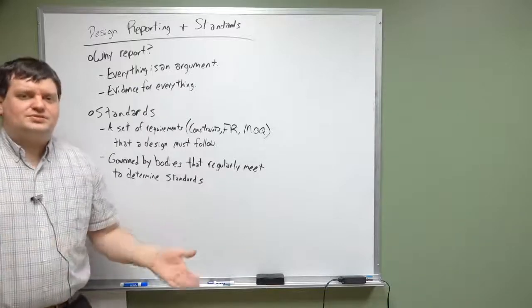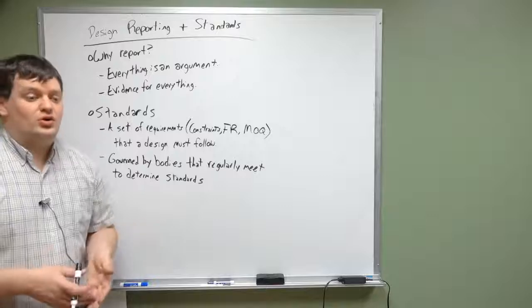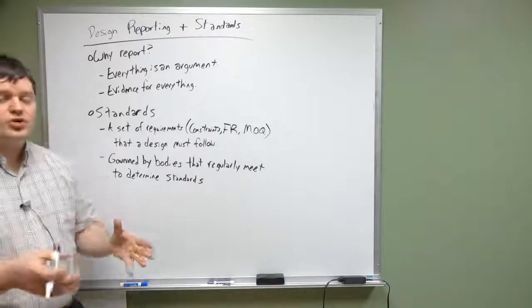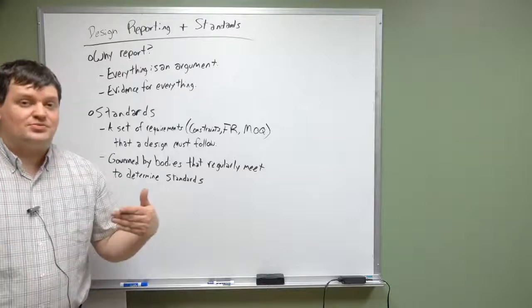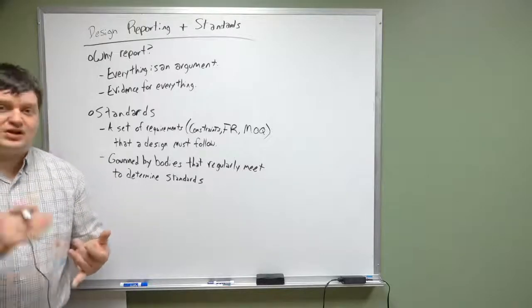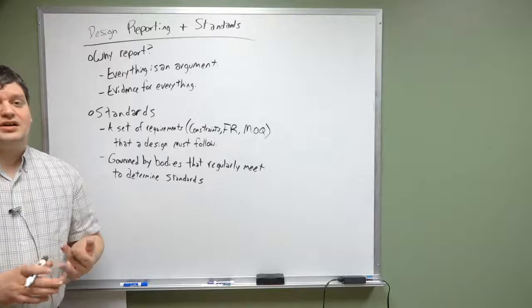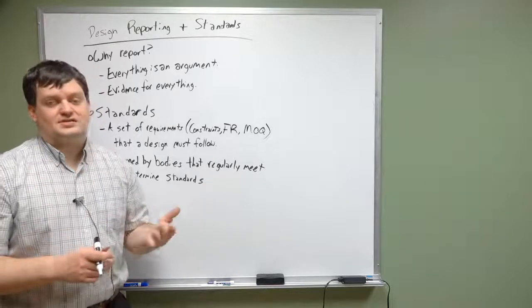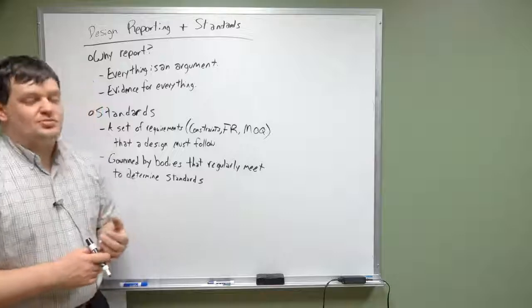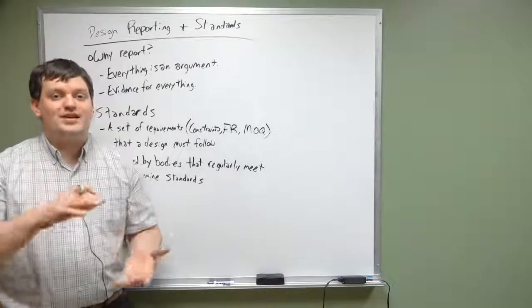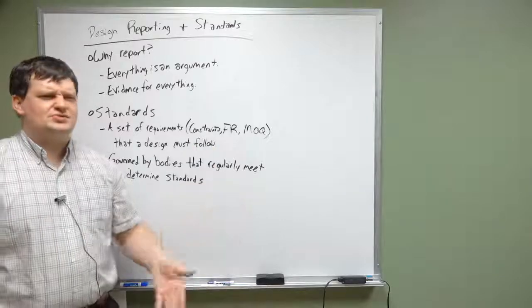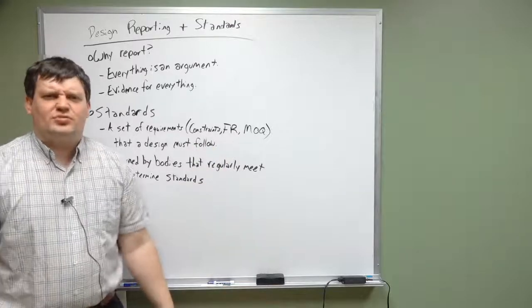A lot of the things you will design in your life will require either the use of standardized hardware, or may themselves be standardized. There are standards for how to develop roadways. A lot of those are set by local governments. Local government, like Crete, City of Crete, specifies that all paved structures that vehicles drive on have to be 7 inches deep. And it has to use a certain type of Portland cement.